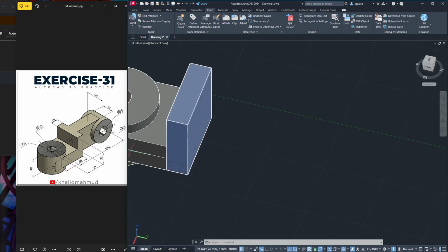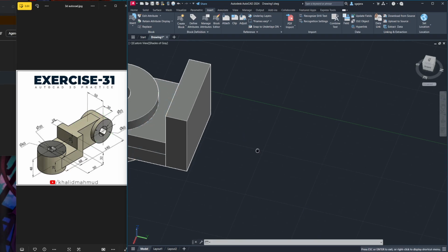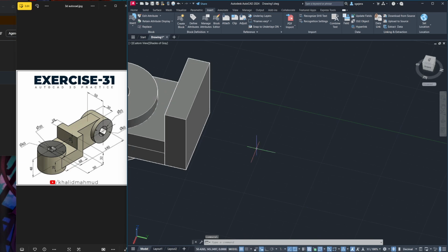And for that, kailangan din i-change yung coordinate system natin. Kasi gusto natin na yung XY natin ngayon would not be from the ground, but actually the XY would be from the right side view. Tama? Itong face na to. So there are many ways to do UCS, no? Pwede namang set tayo ng UCS by manually setting it. Like for example, UCS command. Tapos select tayo ng origin natin. We want it to be at the center dito, no? Para mas madali.